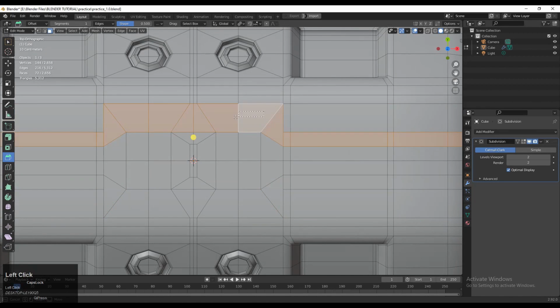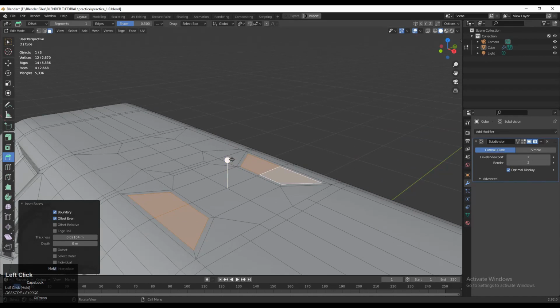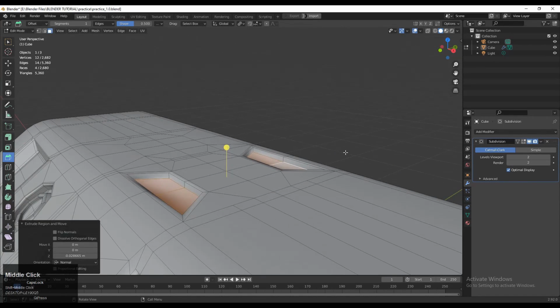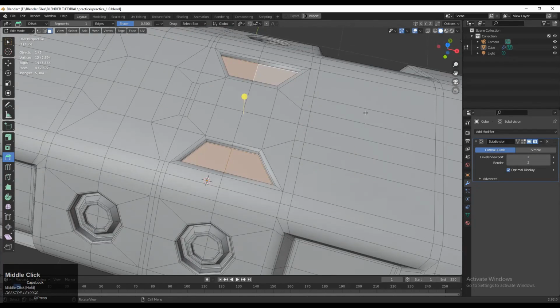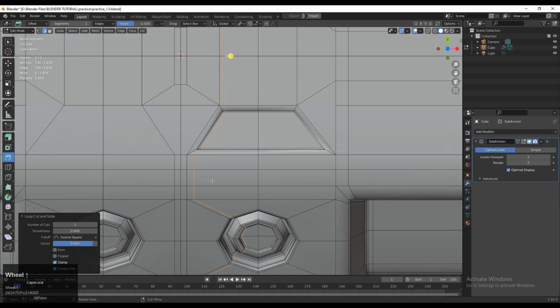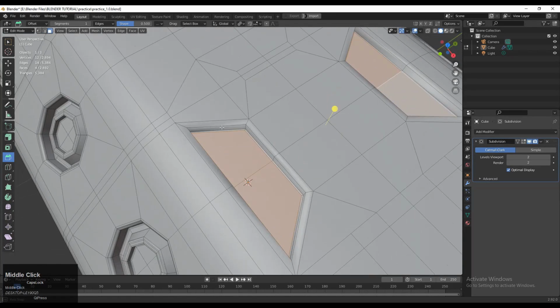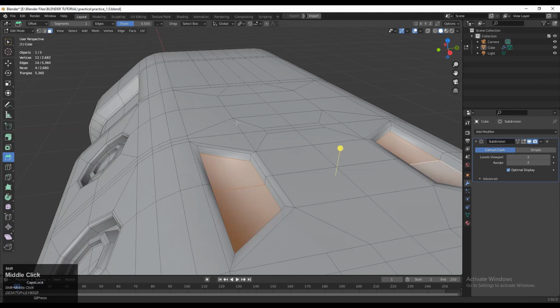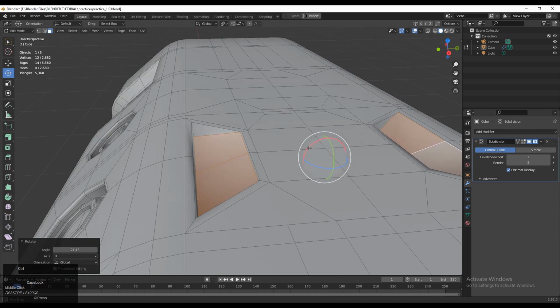And we have got the right topology. So now you can use the insert operation and then extrude it and create a little bit of design there. So press I for the insert operation, and now that looks good. And if I add the loop cuts like this, I will get a little bit of weird result with that cylindrical boolean, and that's fine. We will get the weird result, but we can work on them and we can divert that edge flow and we will be able to get good result also.